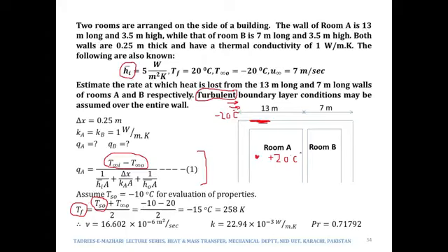See, when the temperature over here is 20 degrees Celsius, and this wall is made of a very insulative material. It is not conductive because it has a thermal conductivity of 1 only. Since this wall has a very low thermal conductivity, there would be a large temperature drop when the heat flows across this wall. Therefore, if the temperature over here is about 20 degrees Celsius, there would be a large temperature drop.